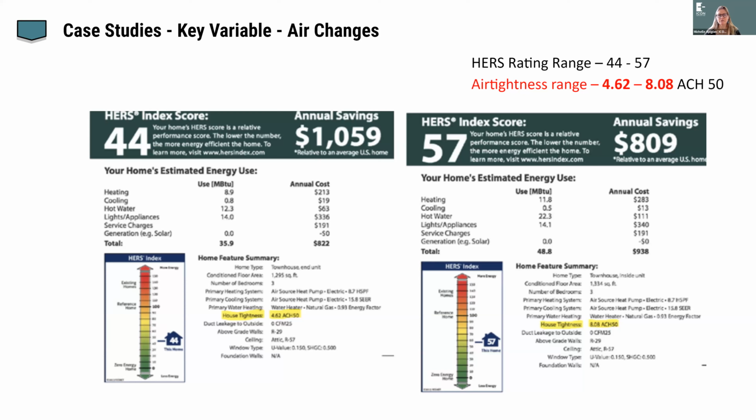You don't get certified. So this is a project that wasn't pursuing Passive House, but it's a multifamily townhome project in South Boston, where we had 2 inches of continuous insulation on the exterior. And Mark talked about these intuitive things that designers start to get comfortable with. 2 inches seems like a pretty solid housing. On a single family home, you might need a little bit more, maybe, with that surface to volume ratio. But the air, so we had 2 inches of continuous insulation.